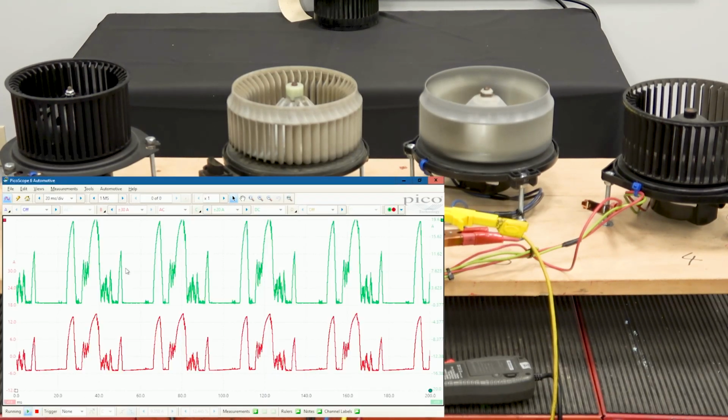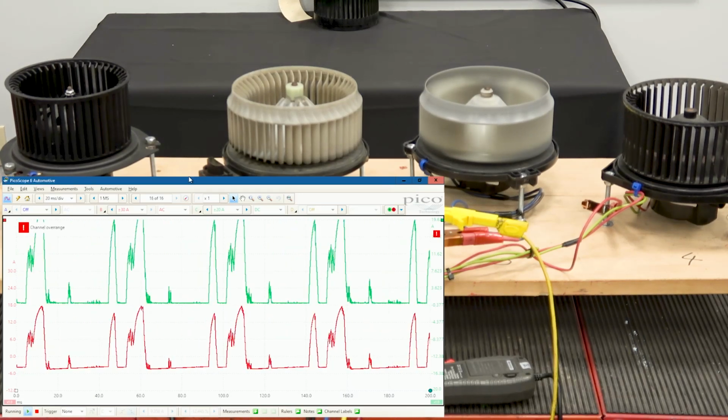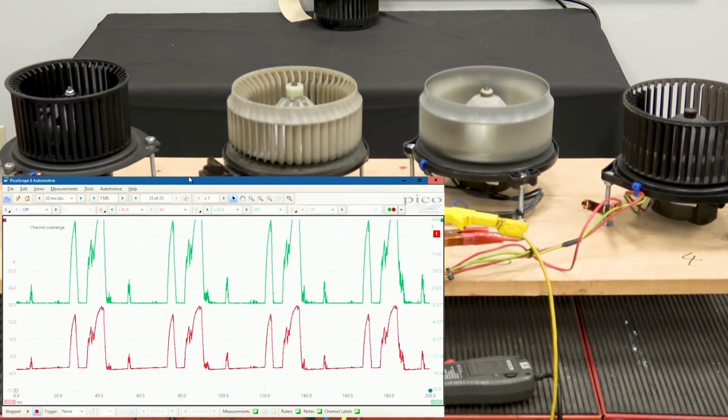And then I'm going to go live. I think you can see here pretty quickly, this has a dead segment, at least one dead segment in the rotor of this blow motor. Now the thing to keep in mind is this motor is turning. You can probably hear it in the background. I think we can switch to that camera and take a look at it. You can see that this motor is actually turning.